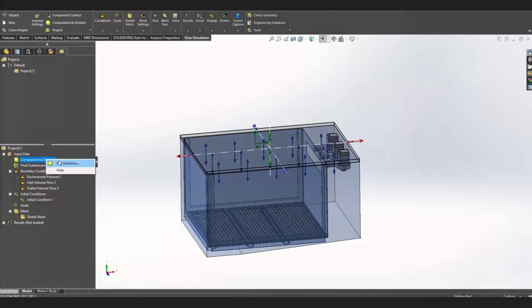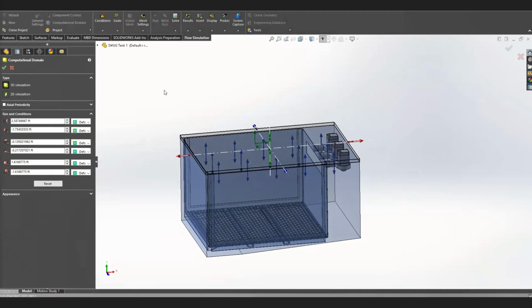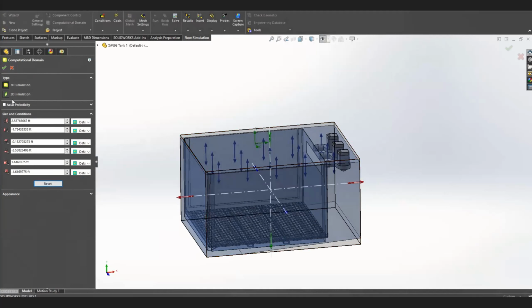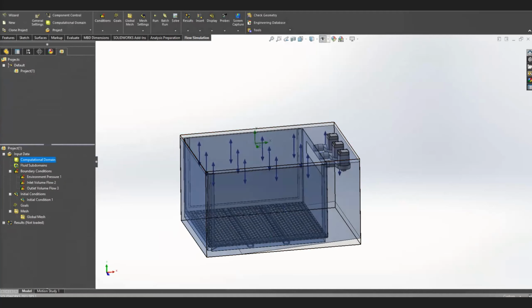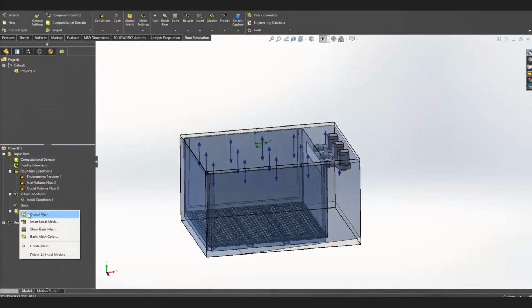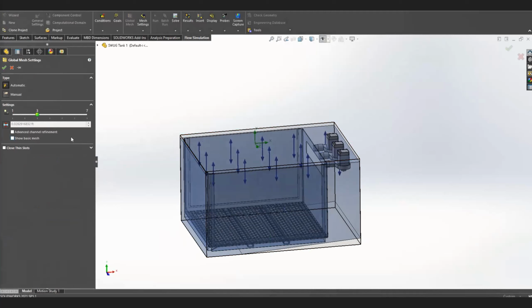And then I set my outlet velocity, like I was saying before, so that there's actually water pumping out, but it's not really going anywhere into the system. It's going out into a black hole essentially. And here now, when I reset the computational domain, you can see it's across the whole water volume.